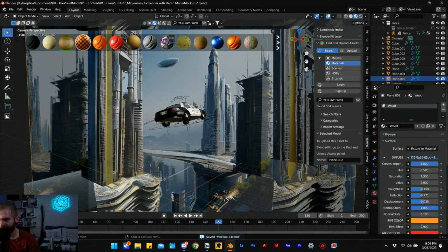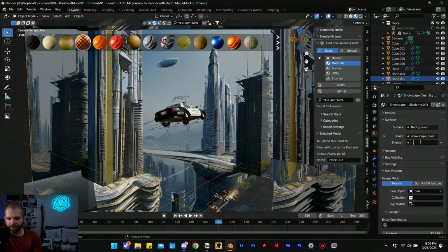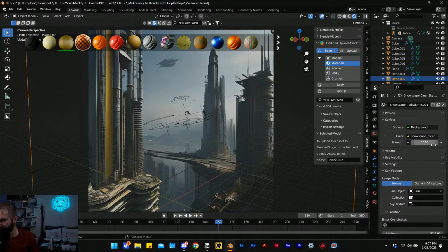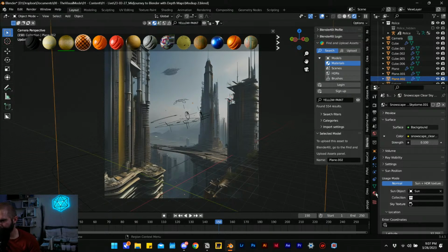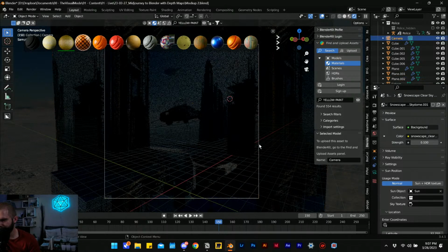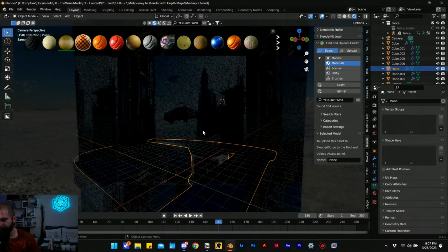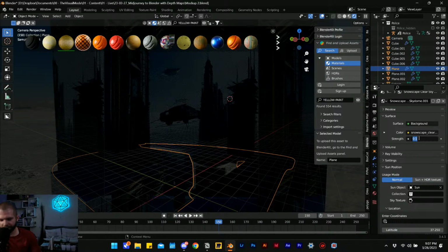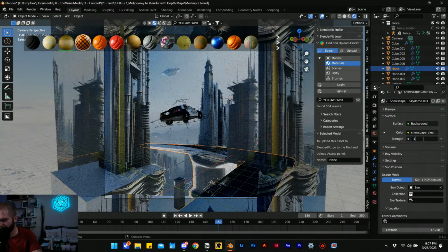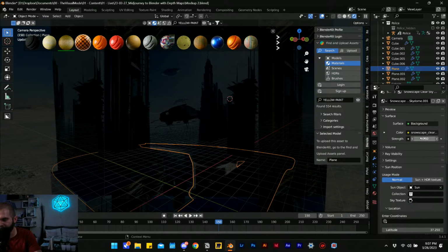But just to get something out of this sequence here, hold on, we're saving quite a bit. So we can go to our lighting. I'm going to tone down the HDRI to like a 0.1. Go into rendered view, and also turn off our background image from the camera. There you go, opacity. Okay, so I toned down the intensity of the environment, like this would be double intensity, do like a 0.1, just to kind of create some really soft shadow. Pick it up to a 0.3.